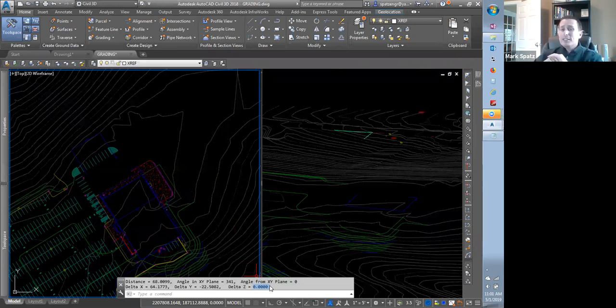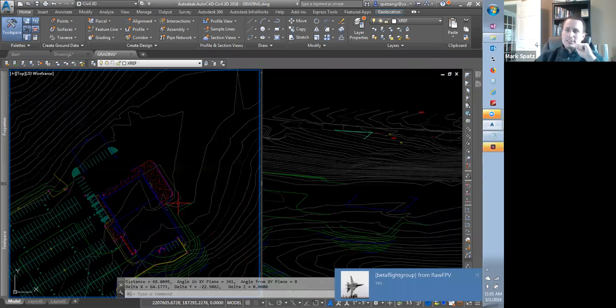That comes into play if you're measuring from one point to another, like a survey point, and you can snap to the node, NOD, to go to the exact survey point. If you don't have OSNAP-Z set to 0, you're going to get the 3D distance. Well, that's not what you really want. You just want the 2D distance, most of the time. I don't think I've ever snapped between points and actually wanted the 3D distance. You just don't want to make that mistake. It could be costly if you make that mistake.